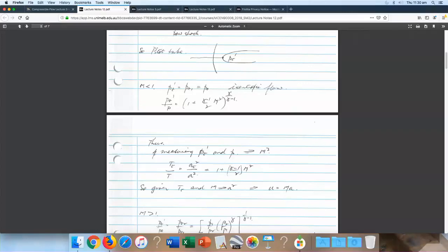And it will be unless there's heat that's being supplied, or there's a massive amount of work done by viscous stresses. So you'd have to be slightly careful. But if it's just reversible flow, then this is isentropic from here to here. And that total pressure will relate to the Mach number.